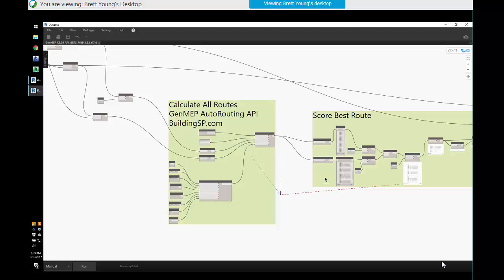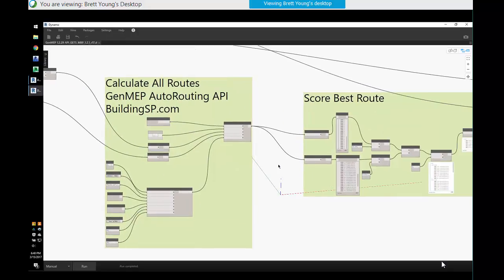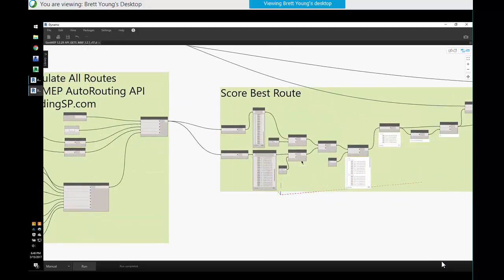Yeah, the thing is, we need to know what connects those two. And so the junction box itself, a generic family, doesn't necessarily have what size and what type of system is connecting between the two. So Revit load information might be able to size the conduit automatically by, this is under 500 watts, so it's probably 3/4 inch conduit, or some number like that. But we need to know in general what Revit conduit families we actually want to connect from point A to point B. And junction boxes usually don't include that. Custom junction boxes probably could, with an electrical connector built into them maybe. So we can come back to this.